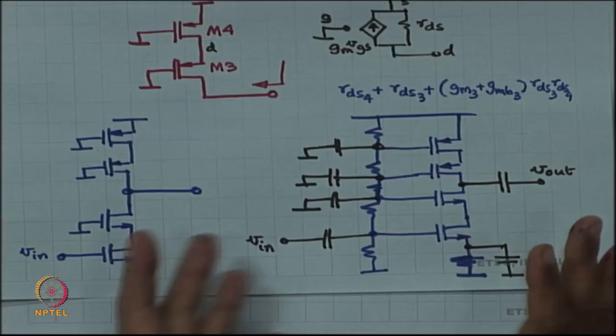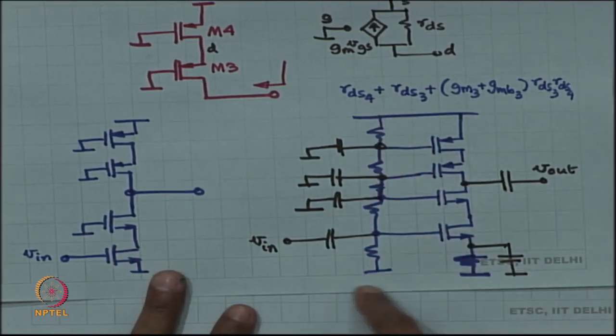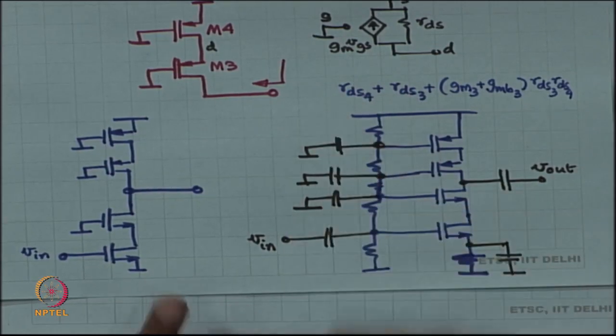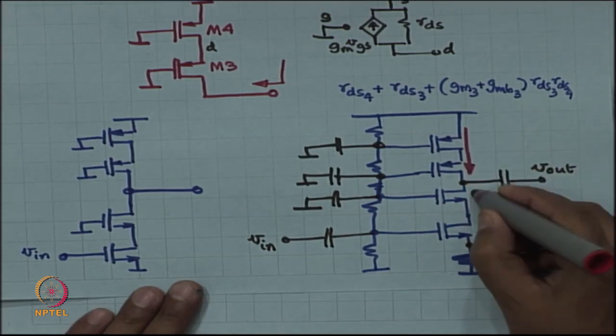I am not yet promising that this works. We have to really think about what this bias network looks like. I mean, maybe it is just 5 resistors like I have drawn, but it is probably likely that these 5 resistors will have to be worked on a little bit, because we have to make sure that all of these carry the same bias current.